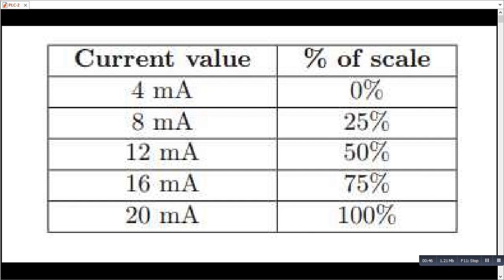And about these values, 4 and 20, this may be answered as follows: when 4 milliampere gets multiplied by the 250 ohm resistance, we get 1 volt. Similarly, if we multiply 20 milliampere with the 250 ohm resistance, we get 5 volt. So this is how we can answer why 4 to 20 milliampere is set, but this is the industrial standard.